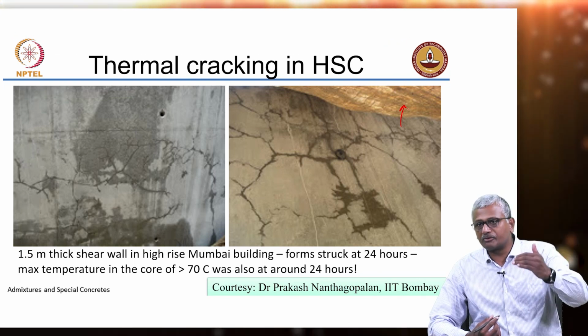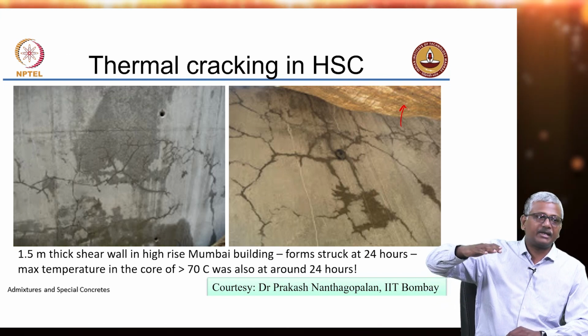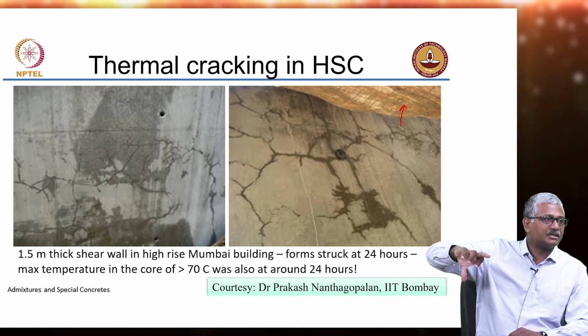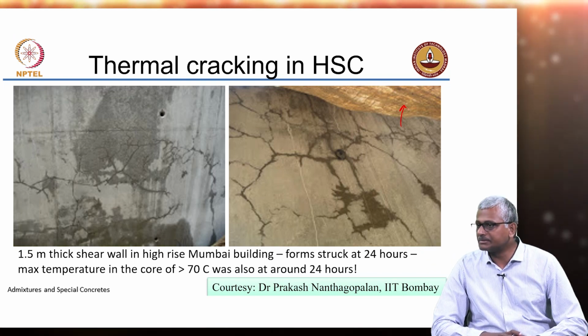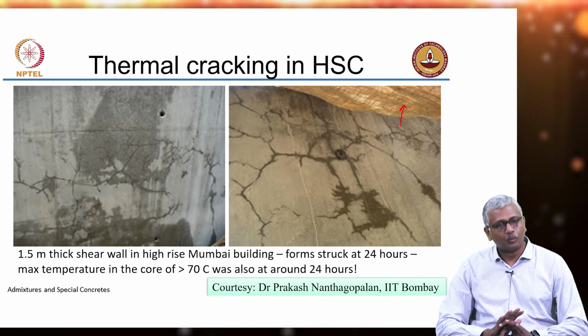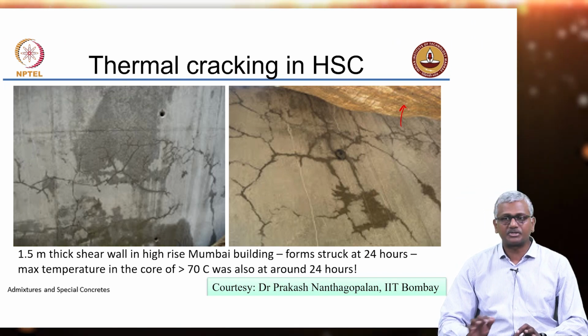The lower temperature of concrete while placement implies the temperature rise will only take it up to a certain level, and the differential between the core and the surface will be reduced. That is the first and most efficient strategy for mass concrete, lowering temperature.